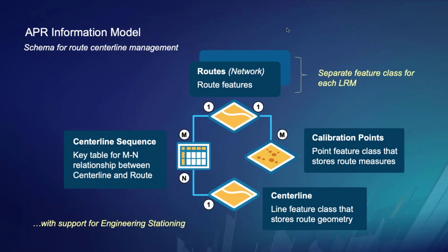So if you've looked at this APR model in the past, this slide is going to be very familiar to you. But what you might not have seen before, when I just transitioned the slide there, is that in the go-forward model, instead of having that traditional geometric centerline that underpins my pipes, the utility network pipe feature class is the centerline for my linear referencing. This will become more obvious when I do the demo, but basically we lay down all our pipes, we connect them together, and then we drop linear referencing on top of those pipes to enable the full capabilities of the platform.